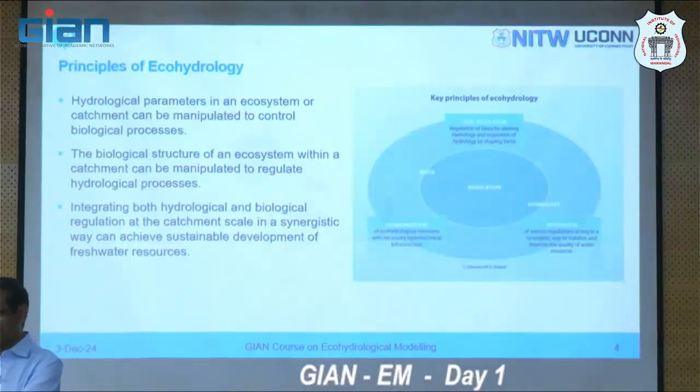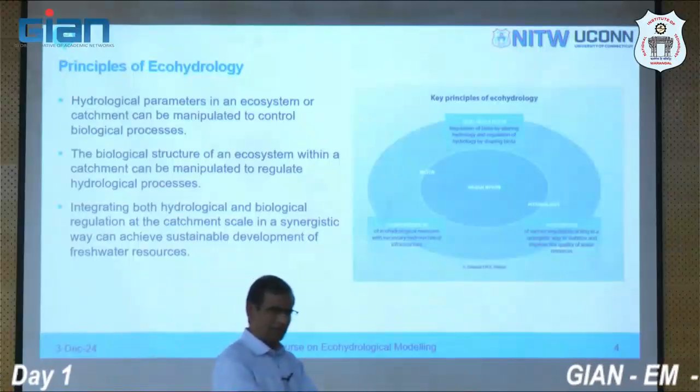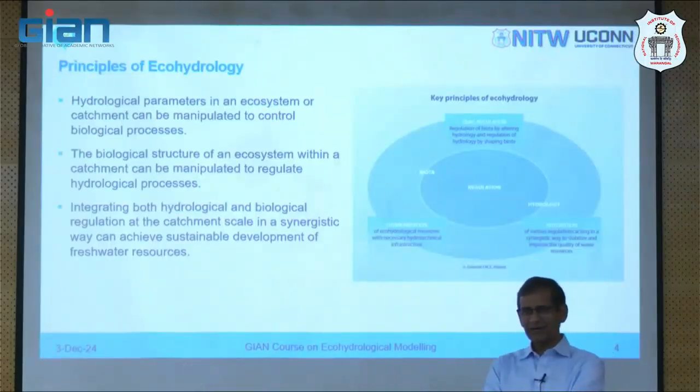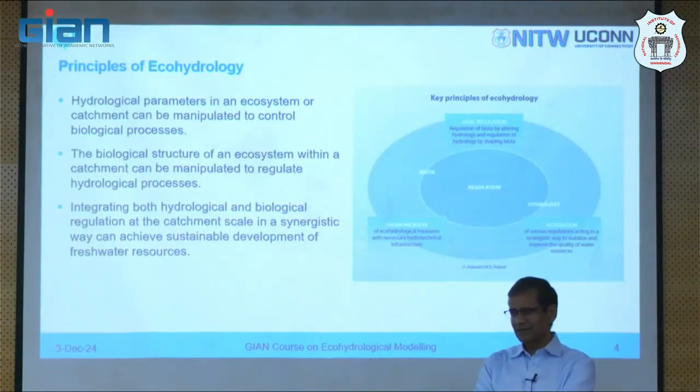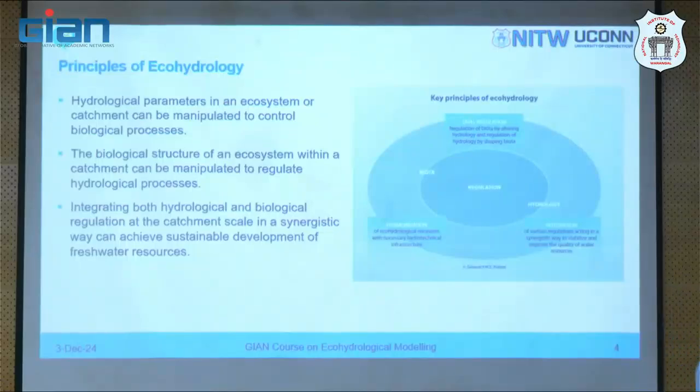Yeah, absolutely. Right? You are connecting the rivers. Therefore, we talked about the minimum flow or environmental flow this morning. And by that, you are going to affect the environmental flow, and that is going to impact the biological response of the river. Right? You can manipulate the flow to create a wetland, and wetland is then going to have a very different biology compared to non-wetland or unsaturated conditions,